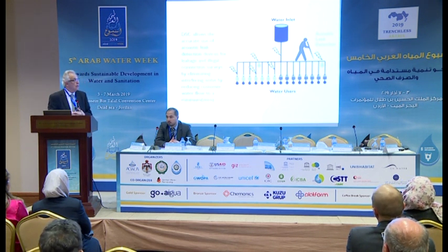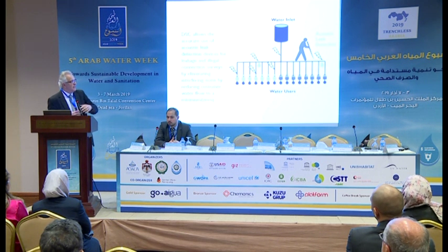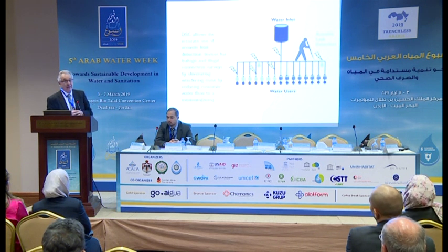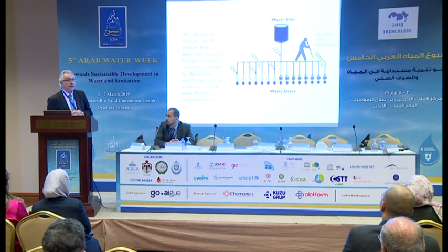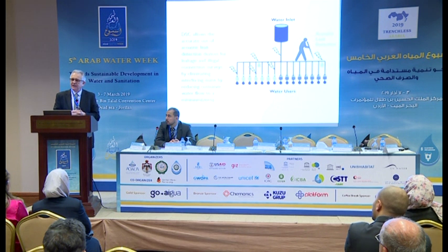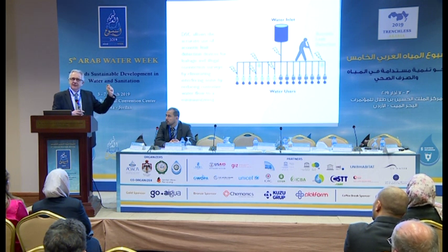We can do active leakage control, acoustic leak detection. In the section of the network that is closed and we have leaks, we can do acoustic leak detection using standard methods of leak detection. Therefore, it becomes easier to find leaks because the network is under pressure.